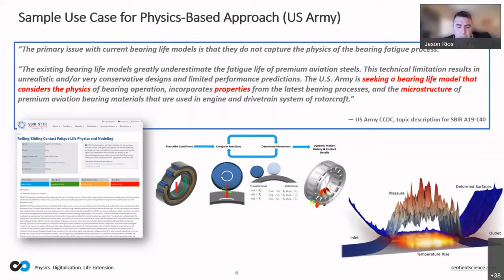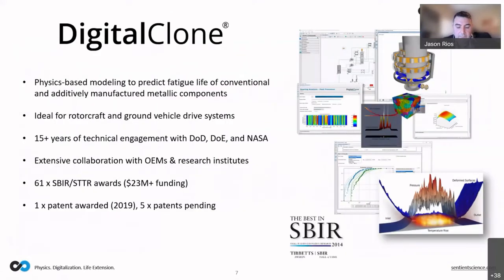It was through programs such as this that my company, Sentient Science, was able to develop a physics-based modeling capability for rotorcraft drive systems, which we call DigitalClone. Its focus is on predicting fatigue life, and it's applicable to both conventionally manufactured components and also to additively manufactured components. We can take additively manufactured components and digitally model and stress them in a virtual environment to achieve the same fatigue life predictions that we're getting on conventional components.